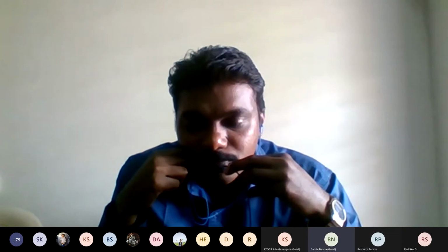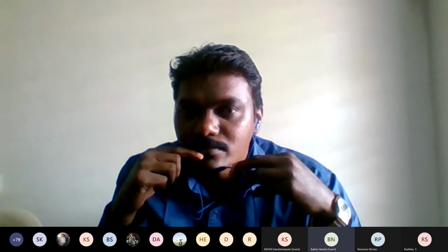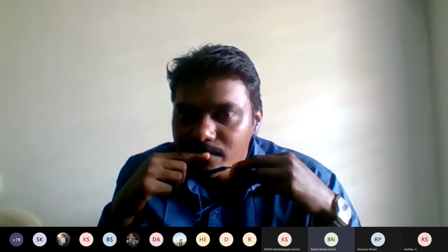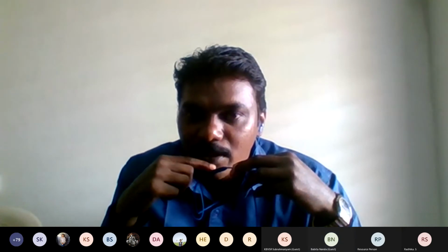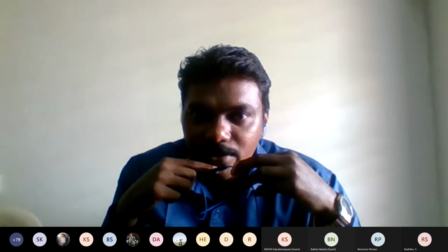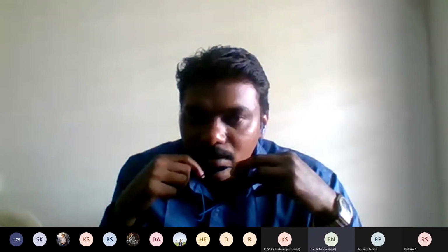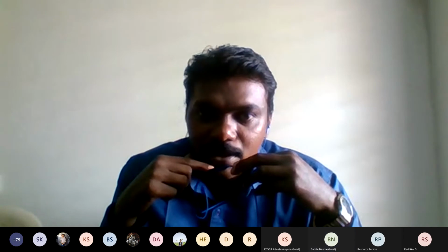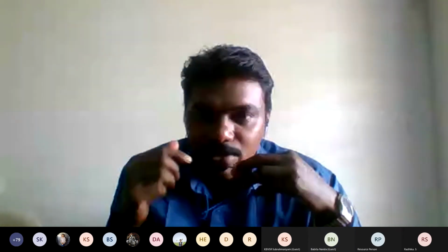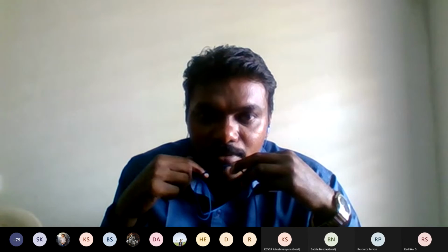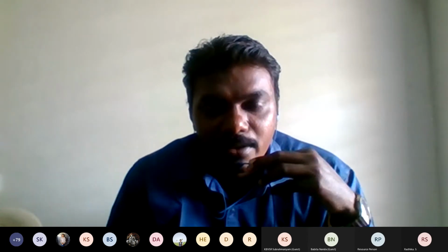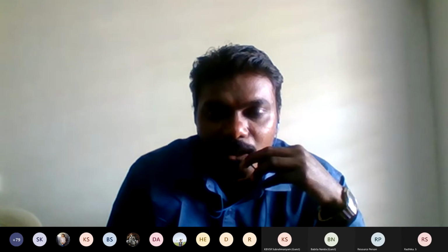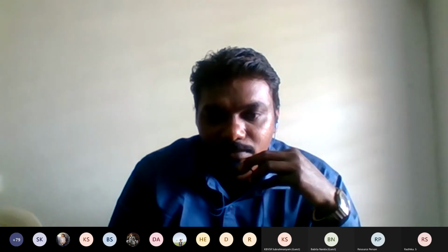Sir, the switching on and switching off, how are you giving it? Madam, after the controller design, from the output of the controller we are getting the DC signal only. By comparing the DC signal with a sawtooth waveform, in MATLAB we are using a sawtooth waveform, but in real time there are pulse generator techniques. By using those components, we are developing the gate signal.